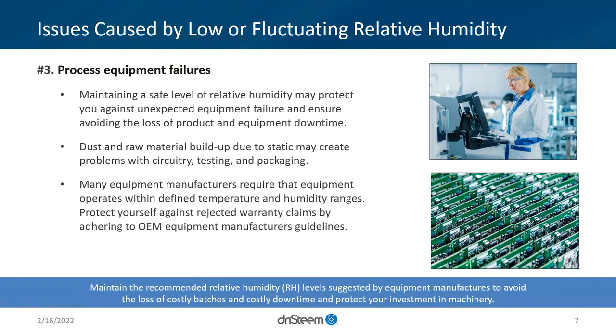Dust and raw material buildup to static. So again, back to having that humidity and getting that air particulate out of the air can help with your quality. The other piece to this, and this is product by product, is the environmental control within these facilities. A lot of OEMs of these different machines will require certain temperature ranges, certain filtration, certain humidity, and we want to make sure we're within that range that they specify.